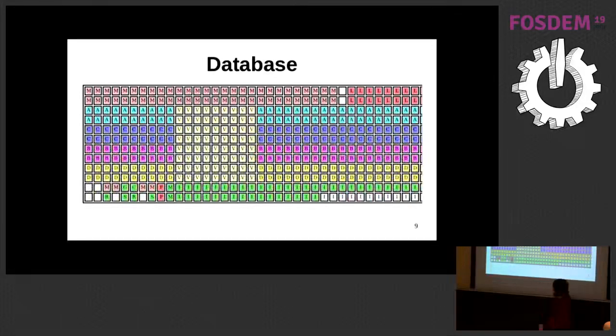So this open source bitstream documentation, this is part of the documentation for a logic tile. This is an overview of what all the bits do. So for example, you have the LUT bits at the bottom, routing bits for the D, B, C, and A inputs, vertical routing bits, some miscellaneous input bits.